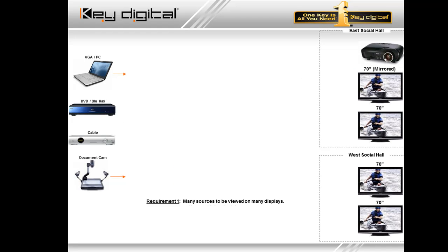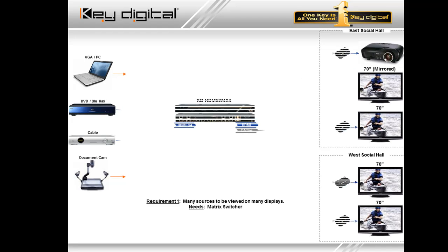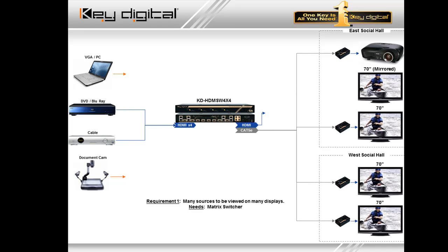Requirement number 1, many to many, requires a matrix switcher. In this case, we're going to utilize KD HDMS W4x4, and I've gone ahead here and connected the baluns that are included with that HDMS W4x4 at this point. Those are included in that kit in the box.